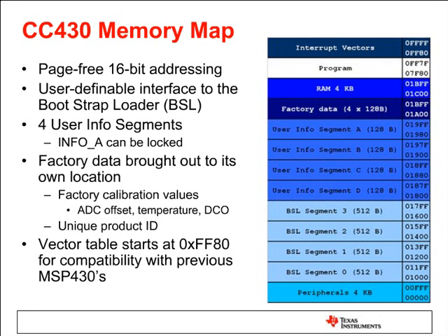You can see the peripherals that are on that device. There's a peripheral discovery table, if you will. We put in calibration data for the ADC12, for the temperature readings, and calibration data for the reference module. A lot of good stuff there in the factory data that I think you guys will find useful.